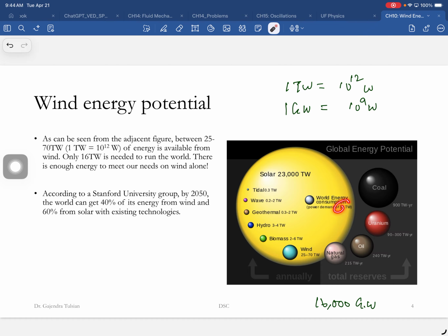It's important that just enough time lapses between two blades traveling through the same location so that new unused wind enters this location. For this reason, the tip speed ratio is the most relevant parameter in determining the efficiency of a turbine. The tip speed ratio is the speed of the tip to the speed of the wind. That's the relevant ratio.